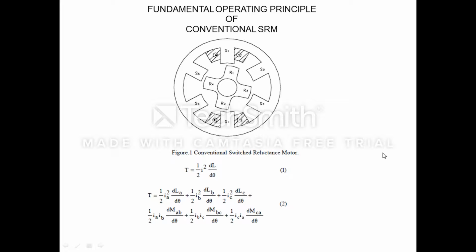As you can see from this image, a conventional short pitched SRM with a single phase excited. It's clear the other two phases will not contribute to the magnetic force, which drives flux through stator teeth S1 and S4 and produces anti-clockwise torque on the rotor teeth R1 and R3.